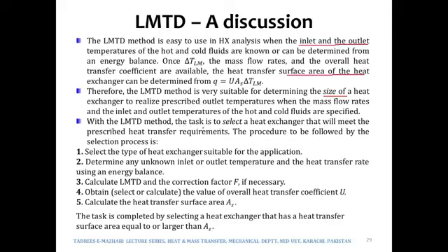Now with this method, the task is to select a heat exchanger that will either meet or exceed the prescribed heat transfer requirements. So the area of the heat exchanger which is available out there in the market should at least be the same or exceed the area as per our calculations. It should be as close to the calculated value as possible, however. So the procedure is as mentioned over here.